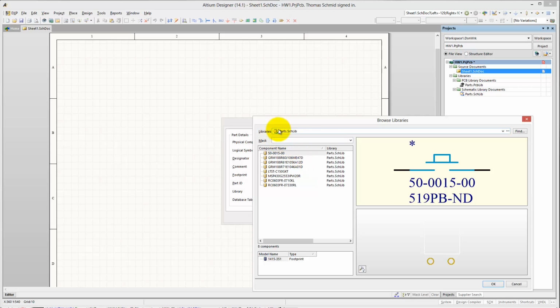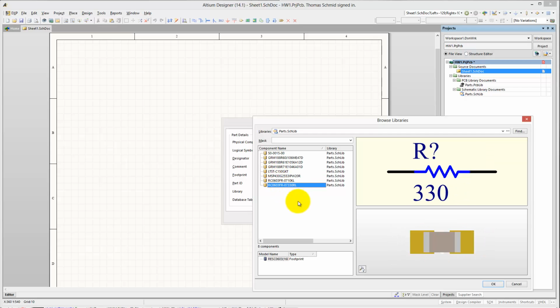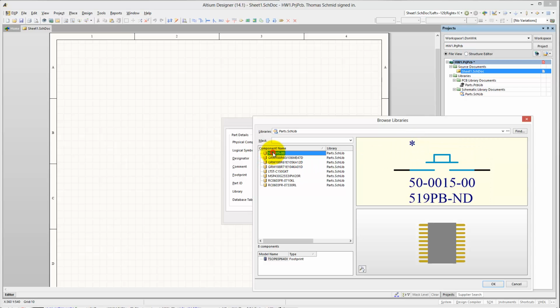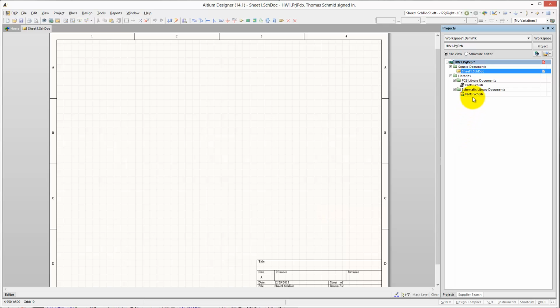You can get them from your parts library, and here you can see the different files or different parts that you can choose from. You will notice that I added a couple more resistors to our device. We have here our microcontroller, which has a nice U question mark here, but if you click on the push button, I actually forgot to change its designator. So let's first go back and actually clean up that library.